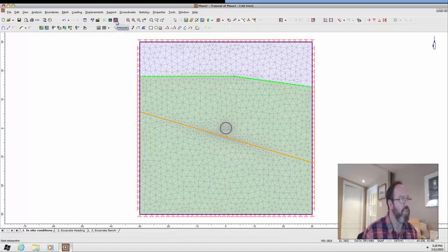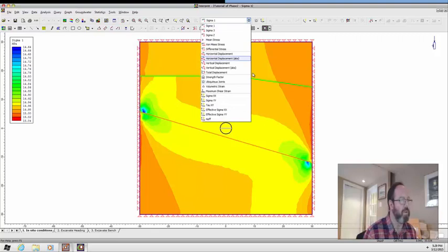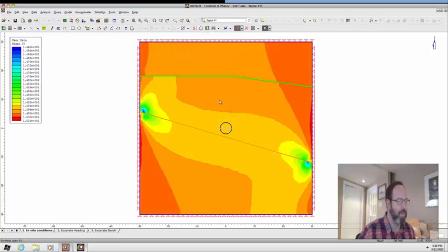So then we go up to the Interpret dialog, and we can see the results. Okay. So first off, let's have a look at the vertical stresses. You can see this drop-down dialog will allow us to look at the stresses in the model, and the contours are shown in this legend over here to the left. So let's see sigma YY, the stresses in the vertical direction.